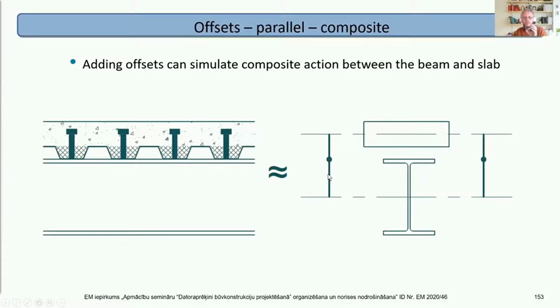You could model the studs explicitly as spring elements, and that will give you a more accurate result. Would it give you much more accuracy for the effort? Have a go. Do an experiment and see if you like the results. And there might be times when it's needed, might be times when it's not.